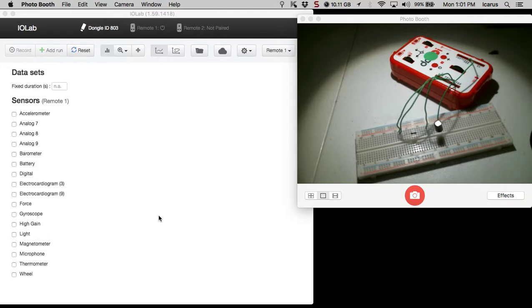Okay, this is a demonstration of the RC time constant lab. You can see my IO lab device is here, and it's rigged up to connect to a 10K resistor. I have connected D6, which is power, to this side of the resistor. A7, which is showing what goes into the circuit, is connected here, and A8 is this green wire on this side of the resistor capacitor pair.